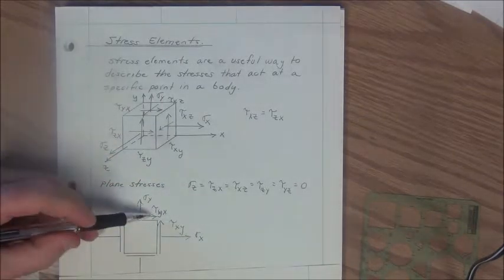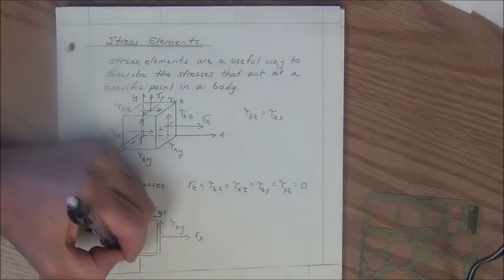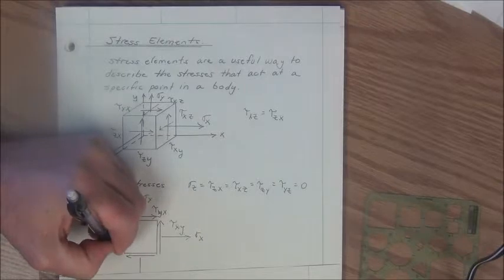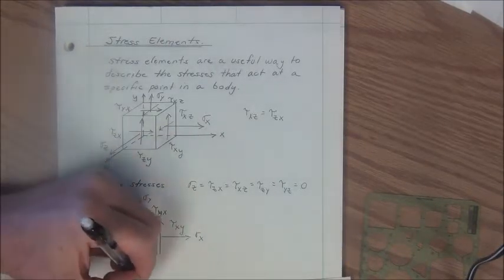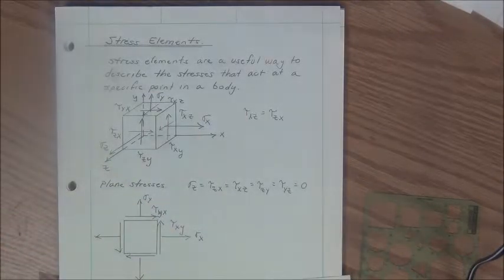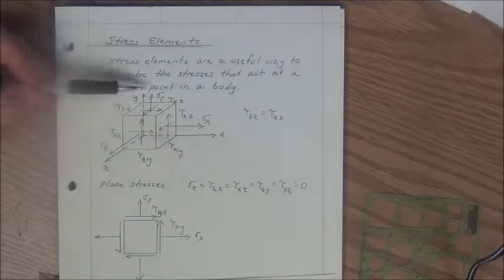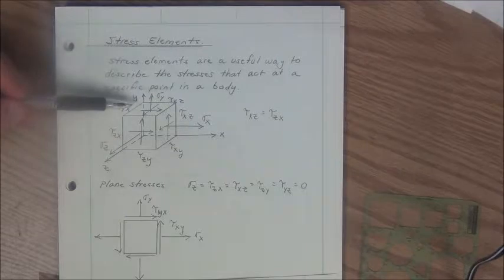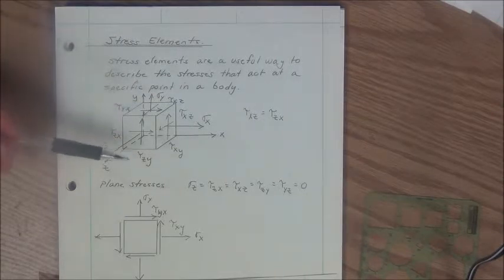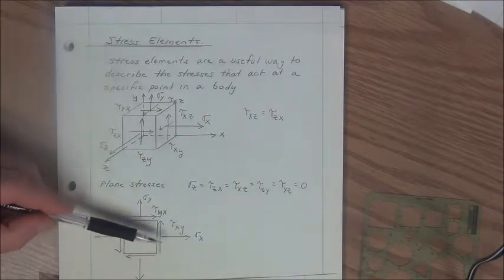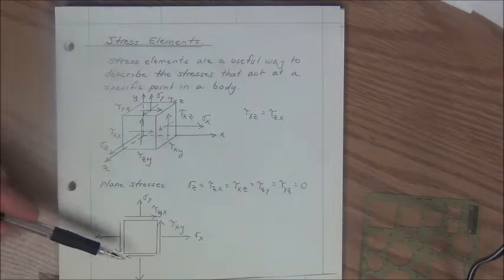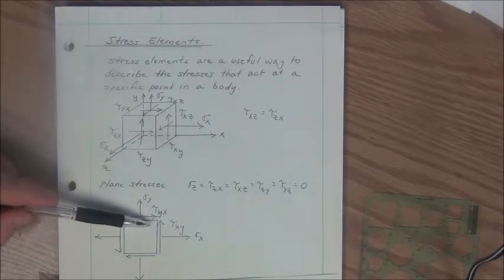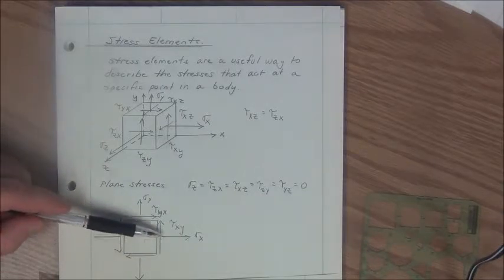And once we draw these stresses in these directions, we know these shear stresses must act to keep the system in equilibrium. And we have now taken this three-dimensional stress element here that is relatively complicated to a simple plane stress element where the full element consists of two normal stresses and essentially one shear stress.